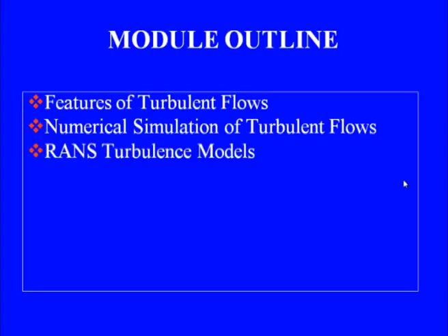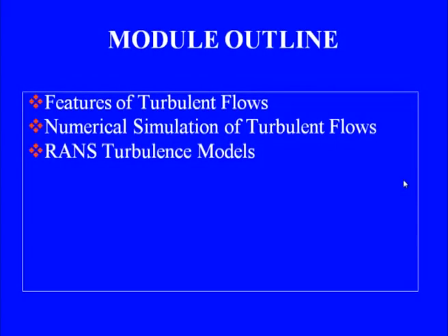We will look at 2 or 3 strategies, in particular what we call a RANS simulation, which is Reynolds averaged Navier-Stokes simulation, wherein certain parts are modeled and there are various turbulence models which are used in industrial CFD simulations. We will discuss some of those models in this module. We will then take up one of the most promising simulation strategies, specifically with increase in the computational power available to us, what we call large eddy simulation.